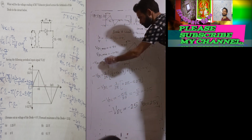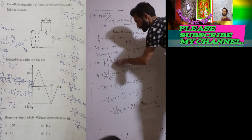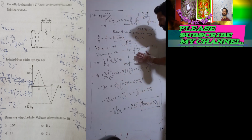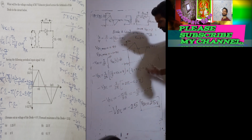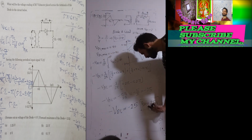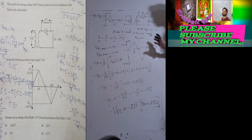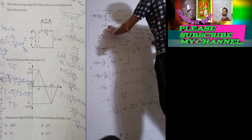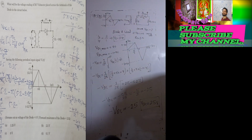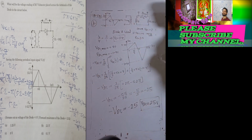So this is 1 by T integration 0 to T of VDC of t dt, which is the area under this curve that we have calculated, and we are left with the final answer VDC equal to 2.5 volt. Okay, so that's all about question number 59, and the answer is option B. Yes, option B is correct for 59.